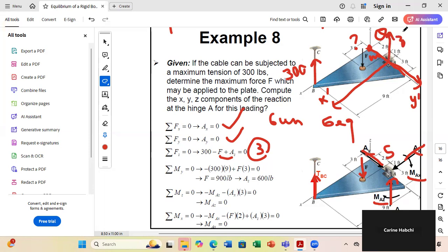They are like X, Y, Z passing by O, but they are passing by A. Okay? And here I also have 2 ways. Either I use the right-hand rule, or I use the cross product. Now in this exercise, they did the right-hand rule. How did they do it? They said first, if I consider sum of moment about this axis, the x axis passing by A, the x prime axis, what are the forces that can do moment about it?